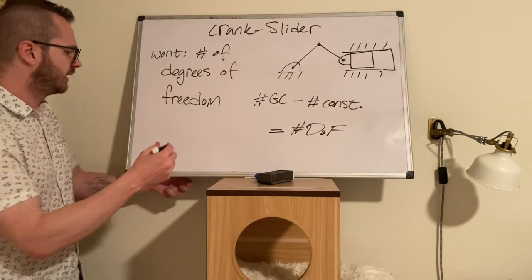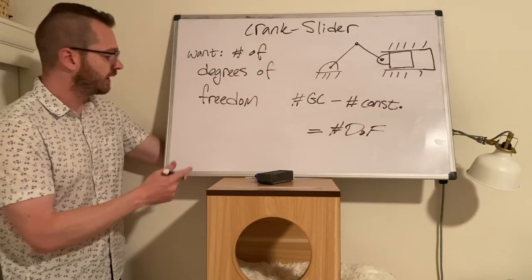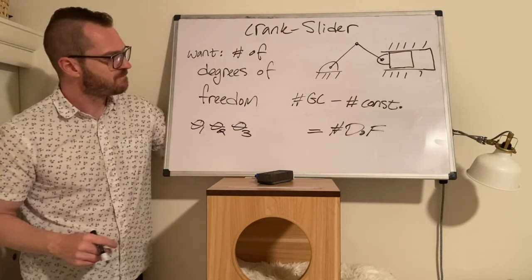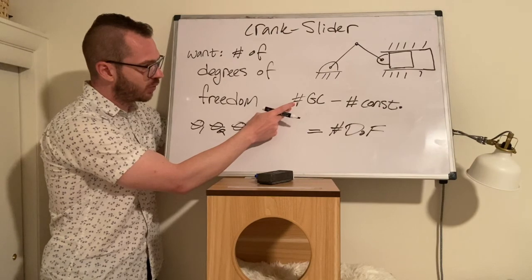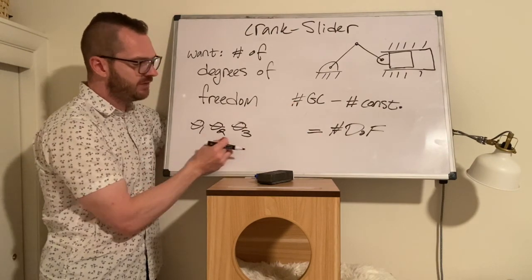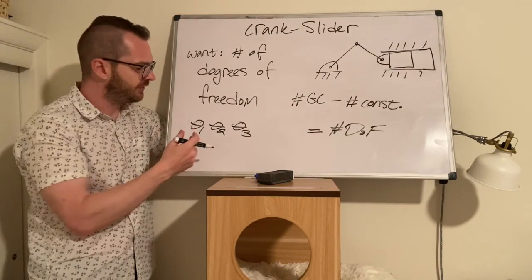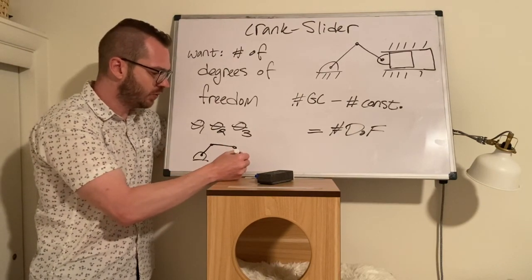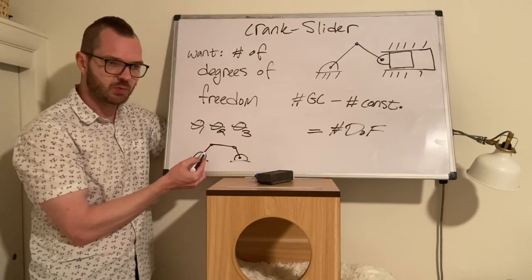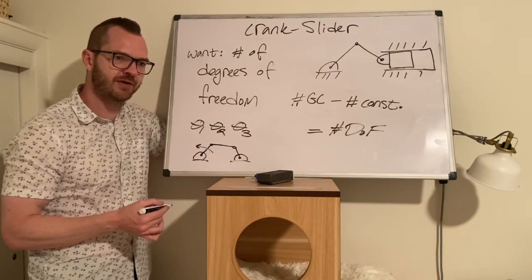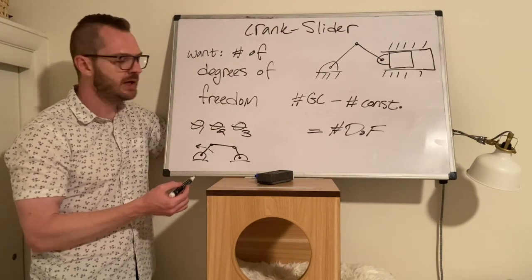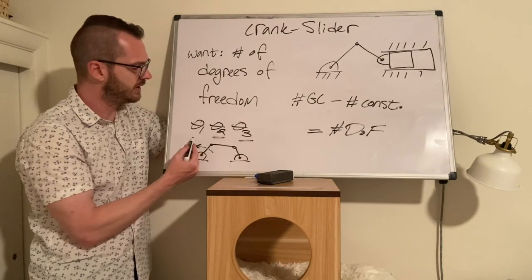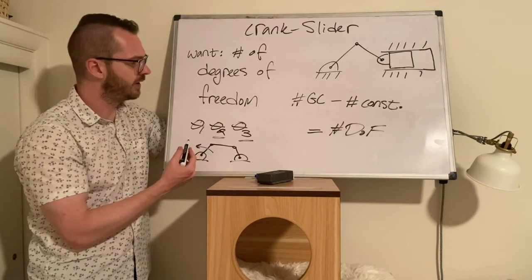So for example, we've already talked about the 4-bar linkage. We said there were 3 angles, theta 1, theta 2, theta 3. There are 3 generalized coordinates. The degree of freedom is how many of these things are independent. So just looking at the diagram on that 4-bar linkage, intuitively, we could look at this system and say, well, there's only one that's independent, because as soon as I move that first one, I make the second one move. And when the second one moves, it makes the third one move. So theta 2 and theta 3 then are dependent on theta 1.